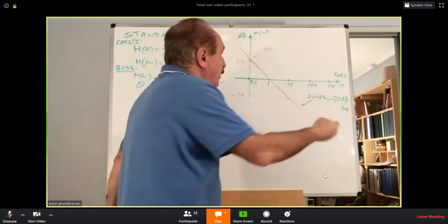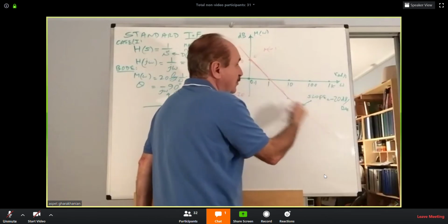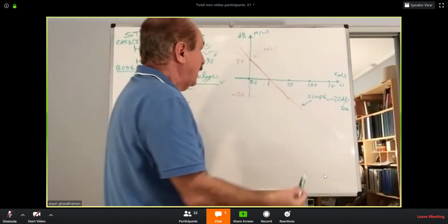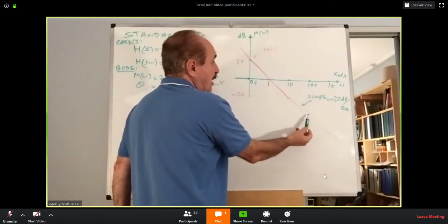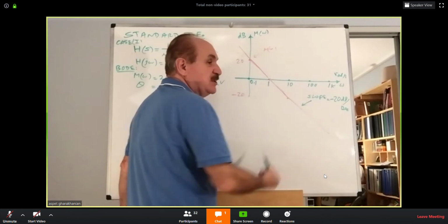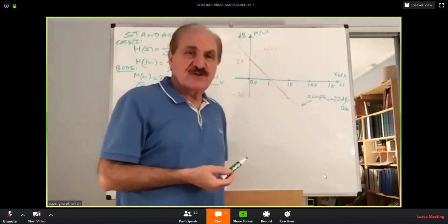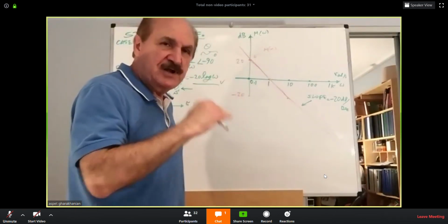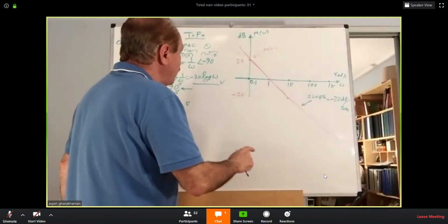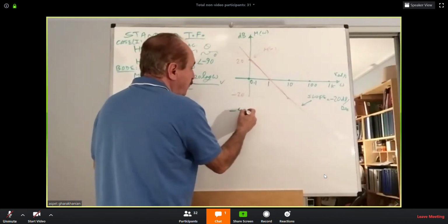It keeps going up and up. From the graph, you can read what the gain will be at 100 radian per second. Here, that naturally will be minus 40 dB. Minus 40 dB is a pretty low gain, an attenuation.